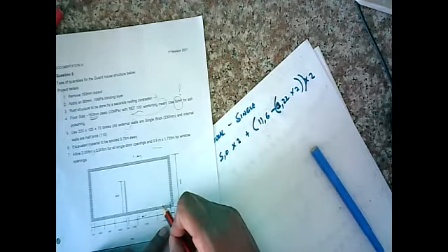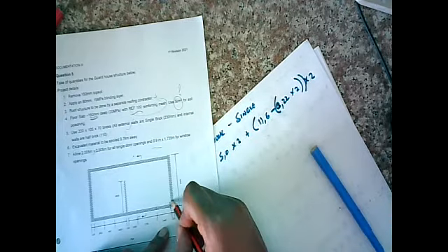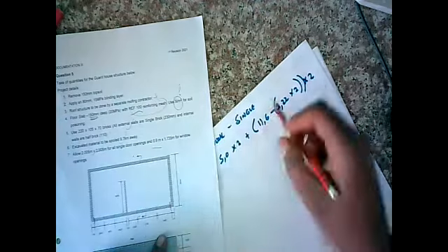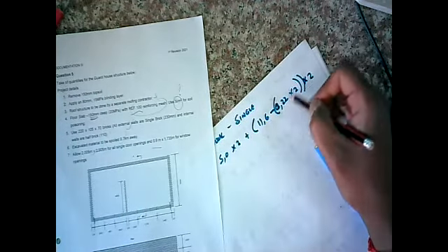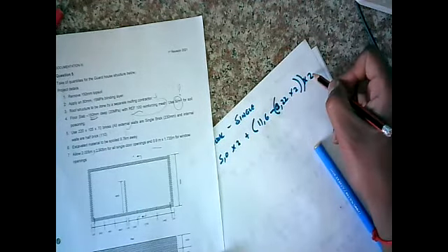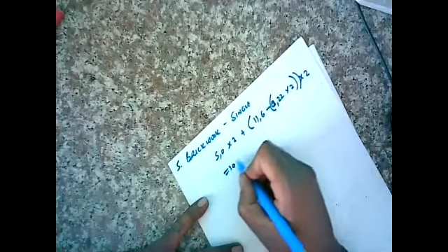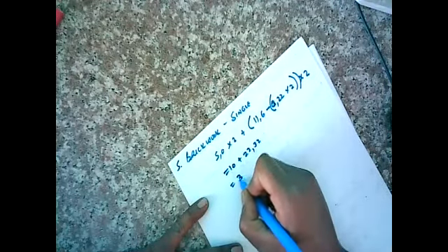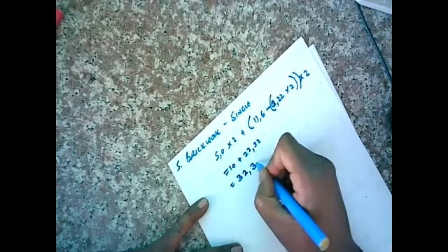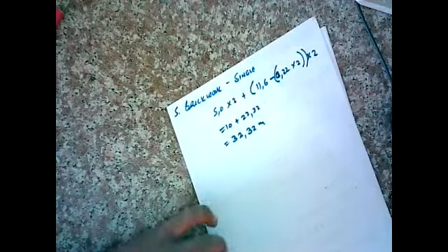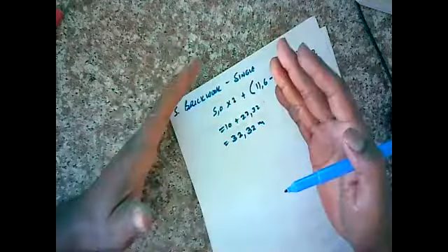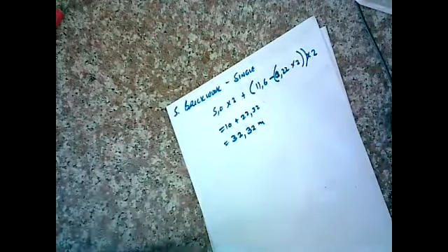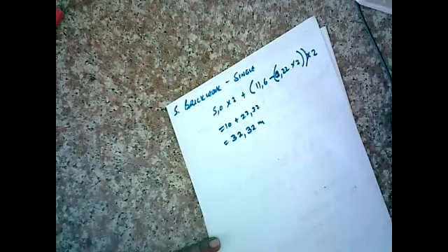So 11.6 is going to be short what? 220 here and 220 there. Here's 11.6, subtract 2 times 220. And the second one is 2 sides. All right. So 10 plus 22.2, and we're getting a value of 32.32 meters. New perimeter to deal with. This time is for brickwork.